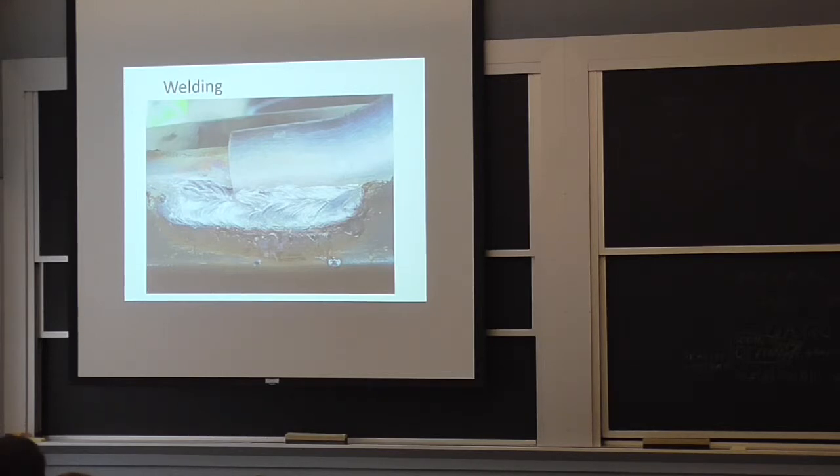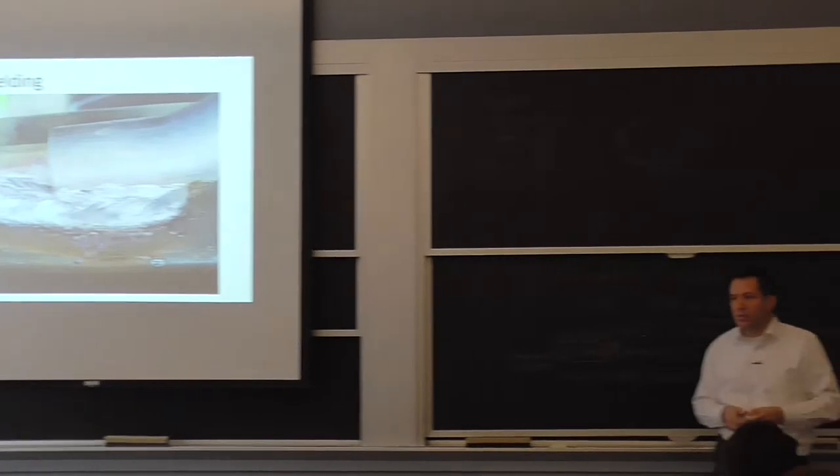One reason is you really melted the material and cooled it off really, really quickly. So you definitely change a lot of things in terms of what we discussed earlier with steel and aluminum to try to optimize the material. Now you have a cast structure, you have segregation, and you have residual stresses because you're cooling so quickly from something hot, so there's going to be tension in that weld.